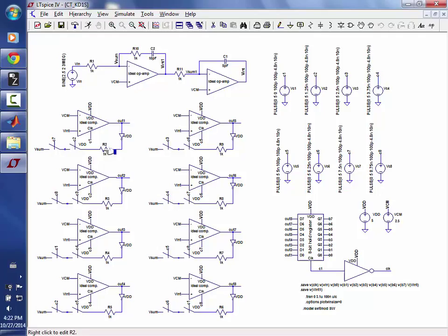So if we were running at 100 megahertz, this resistor would be connected for 1.25 nanoseconds. If there is a 0 or a 1 here, it's connected and discharges or charges the capacitor for that short period of time. So you notice now we don't have to worry about the scaling. This resistor can be the same size as this one, and if the periods are 1/8, then you can get the right magnitude response.